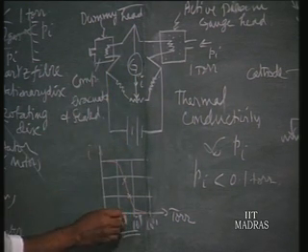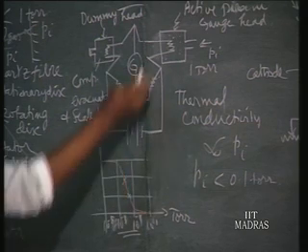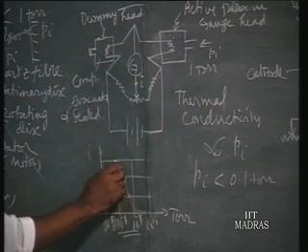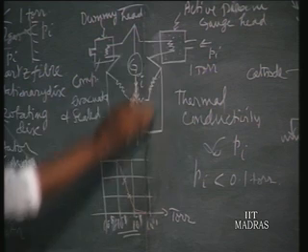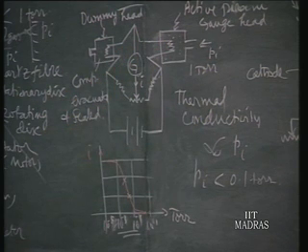So as the vacuum is increased, the imbalance increases because resistance keeps on increasing, though current is decreasing. This is the calibration curve. Later on, for the same gas, unknown vacuum pressure can be found out by this.